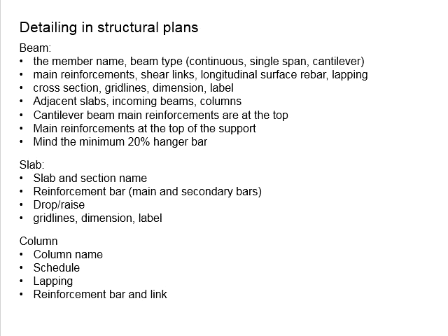Next, remember the cantilever beam. It acts differently from the continuous and simply supported beam. The cantilever beam will have compression at the bottom of the beam and tension at the top of the beam, which is the reverse of typical beams. In that case, the main reinforcement bar will be on top of the cantilever beam. And when you come to the cantilever beam, you will need to be careful, as typically the engineer will design it more conservatively to avoid failure due to the cantilever.